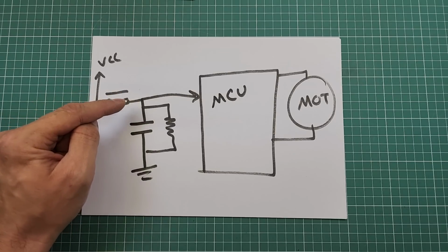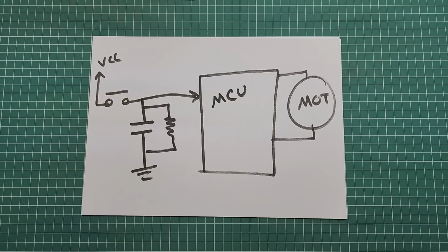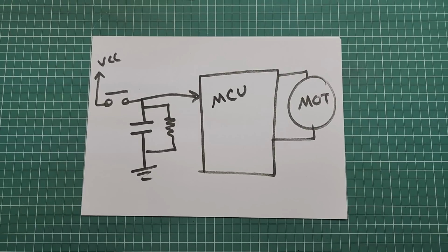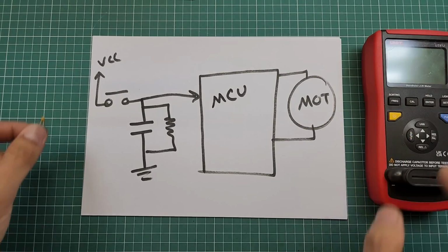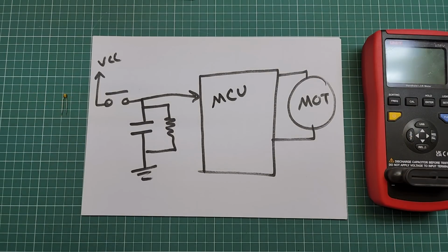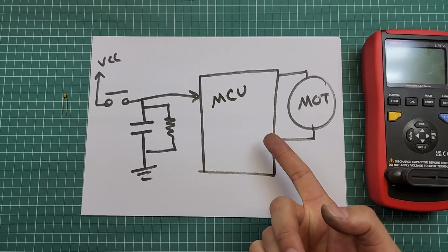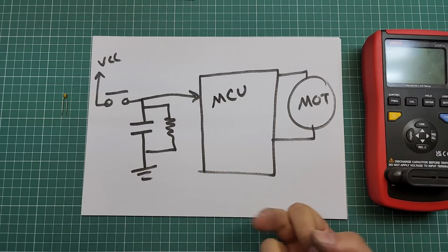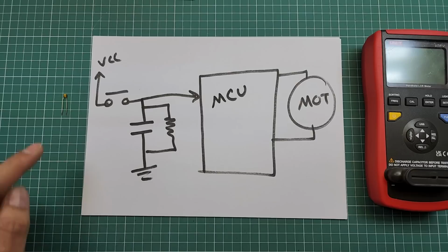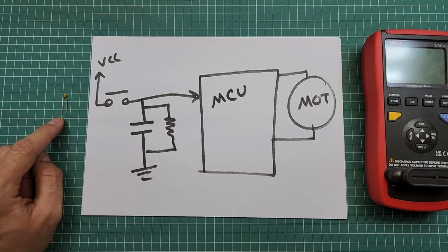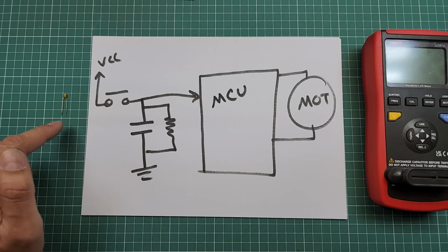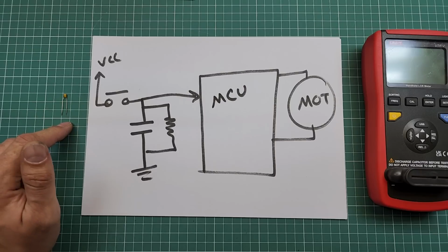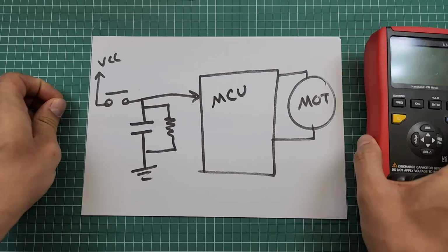The capacitance value of this capacitor has a direct relationship with timing. So we have to choose a stable capacitor to have a stable time. Suppose that this circuit here checks the voltage of this capacitor and turns this DC motor on if the voltage of this capacitor is not zero. These ceramic capacitors are not a suitable type for timing because they are not stable, just like electrolytic capacitors that we tested before.